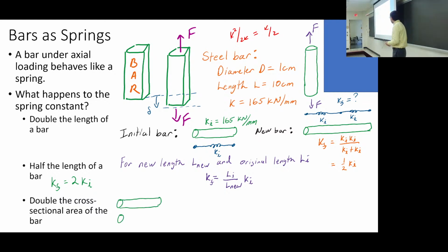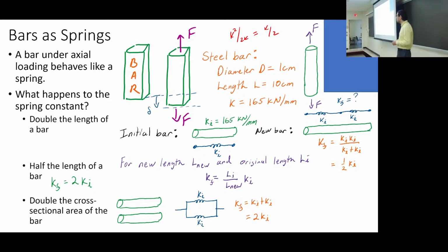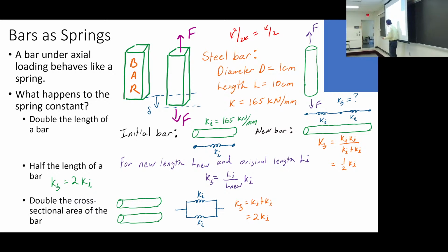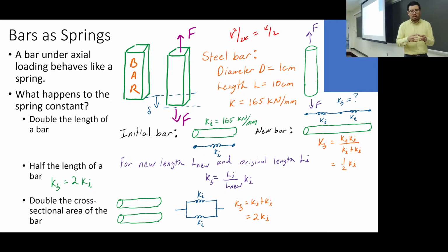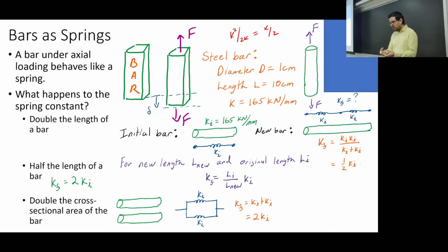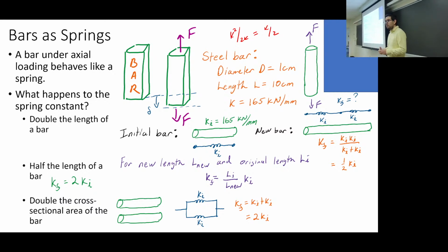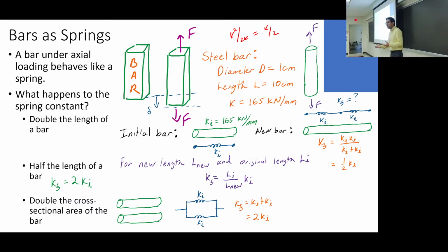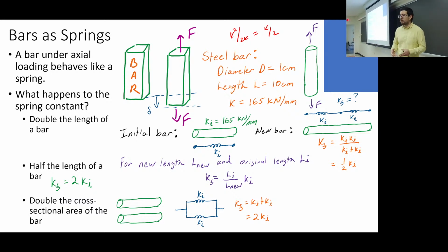So essentially, we can write it out like this, okay? We now have two springs in parallel with each other, and we can double the stiffness. Now, granted, this looks like a system with two bars in it. When I say double the cross-sectional area, I could just be putting two bars in parallel with each other, or we could be increasing the diameter appropriately. Right now, with d squared, it comes out to the square root of 2 essentially, if I'm going to increase the area by a factor of 2.